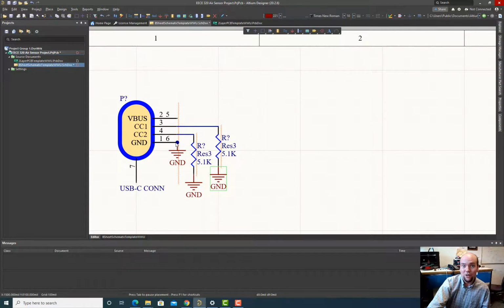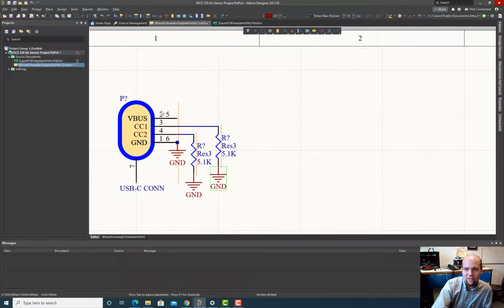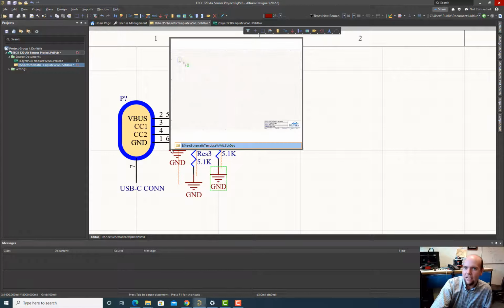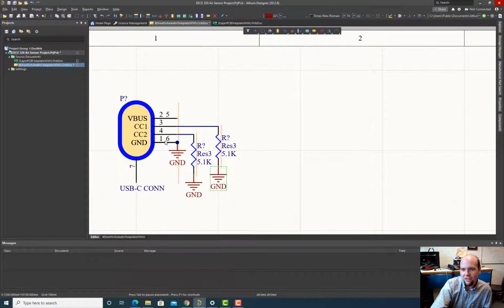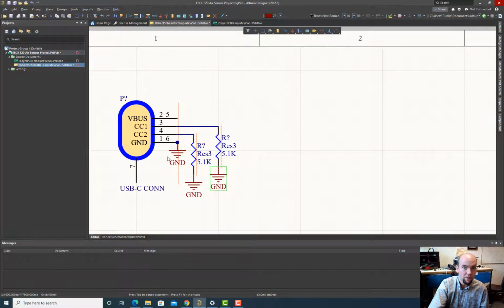And so it gives us a big blue dot to tell us, hey, you're connected to more than one thing here. So it's good for your eye to know that. The reason that's a little weird right now is because you don't see that it's 2 pins, but that's how we got the 2 pin labels here. It's kind of a downside of Altium. Most of these EDA softwares allow you to take a pin and specify that this pin maps to 2 physical pins. In Altium, you kind of just have to do 2 overlaying pins. You have to do this sort of a trick.